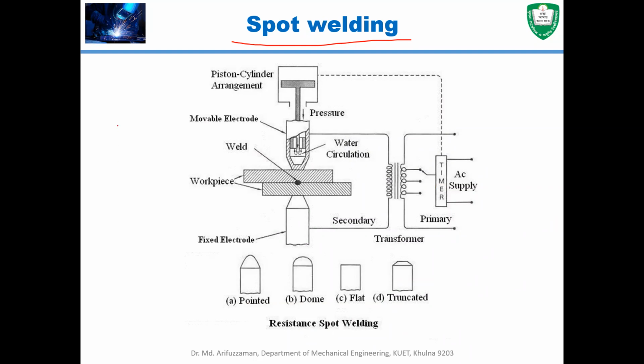For example, if you have looked at transformers, they have some fins like this, right? Those fins are joined around the surfaces. Or if you look at automobile bodies, different sheet metals have to be joined together at various spots. To join them together, you can use spot welding. It is very convenient, takes a very small amount of time, and gives you a very convenient joint. Okay.